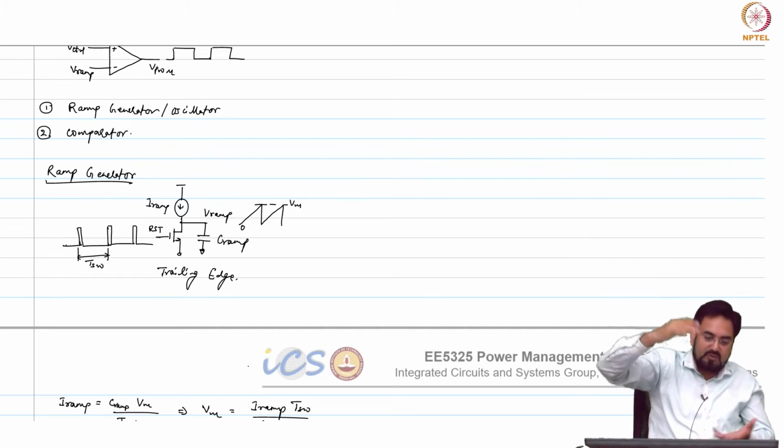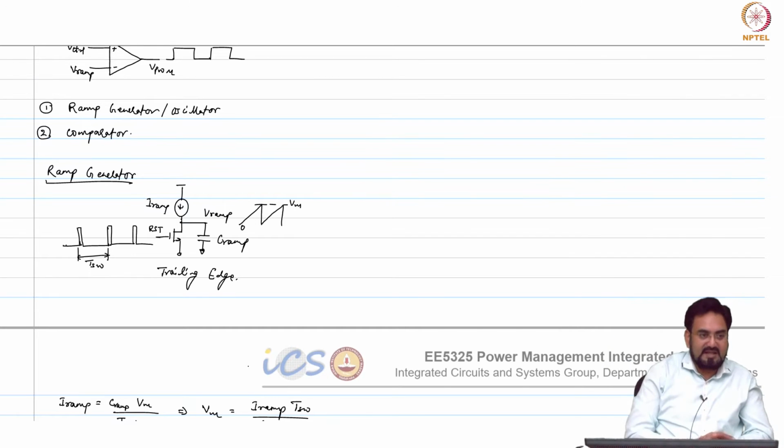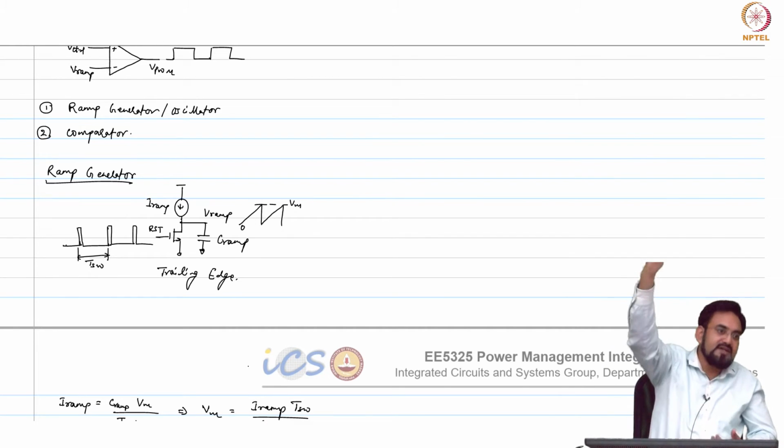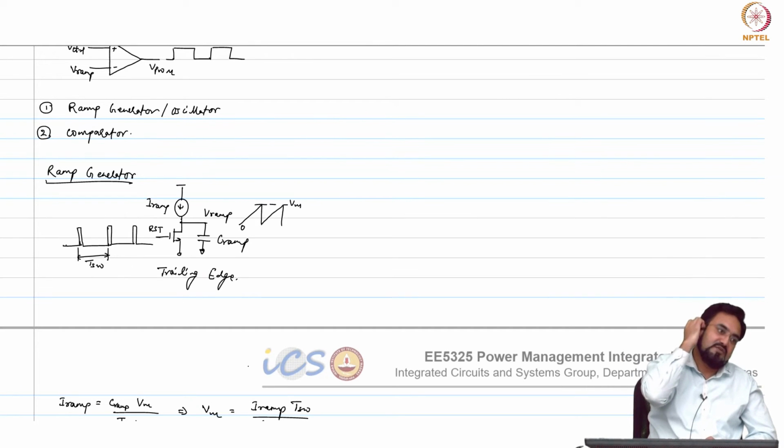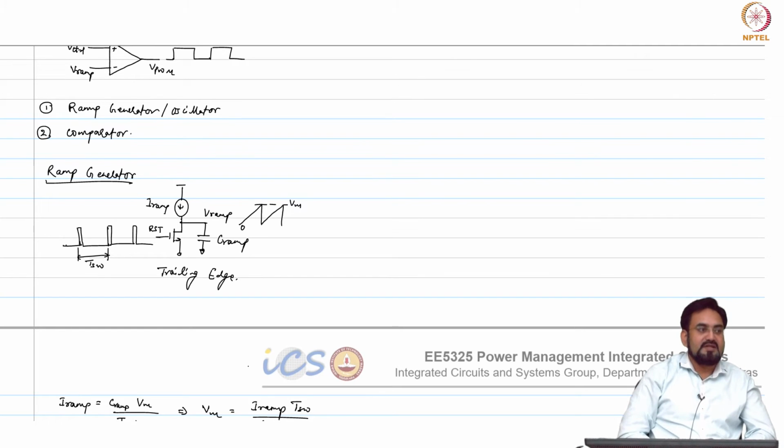So you have to see where you are limiting the duty cycle, whether you are hitting the voltage where one of the devices will go into saturation or not. Okay. So, let us say my range is maybe 20 to 60%. In that case, the other case may work.